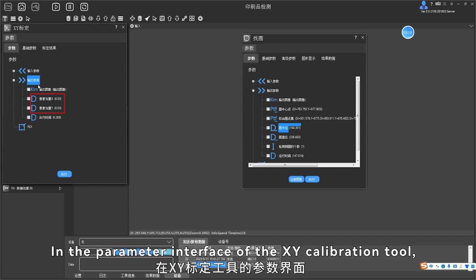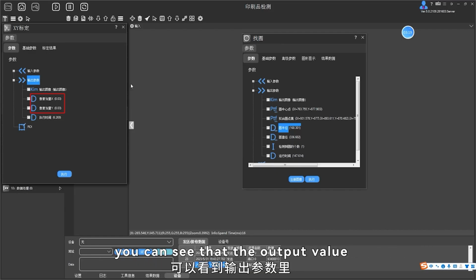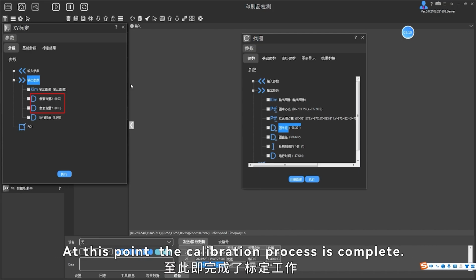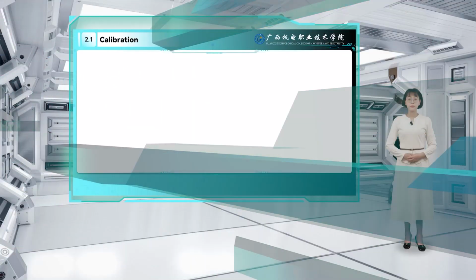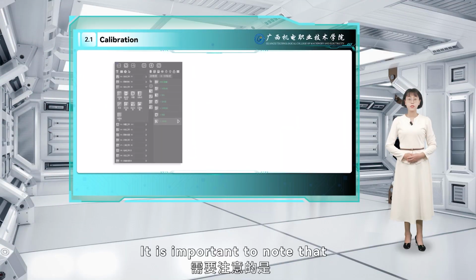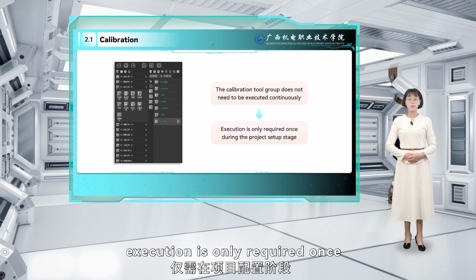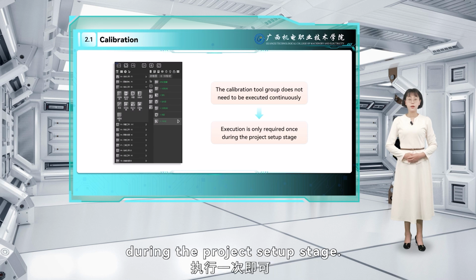In the parameter interface of the XY calibration tool, you can see that the output value of pixel equivalent is very small, which indicates that the XY calibration is successful. At this point, the calibration process is complete. It is important to note that the calibration tool group does not need to be executed continuously. Execution is only required once during the project setup stage.